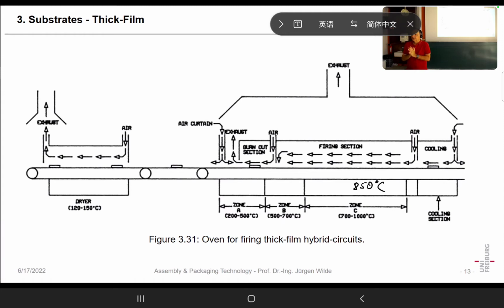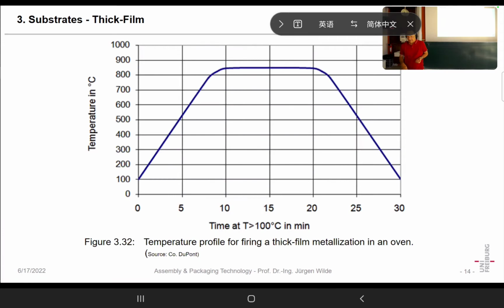So, of course, you must not cool such ceramic substrates too fast after the firing, or they might crack, because ceramics are brittle, and also in that way you can generate defects either in the substrate, or if you have a glass layer on it, possibly that glass can crack. Okay, that is just such a firing profile with a well-defined rate, keeping it for a time, for instance, 10 to 12 minutes, cooling down at a certain rate. And that is just an example for the firing step.